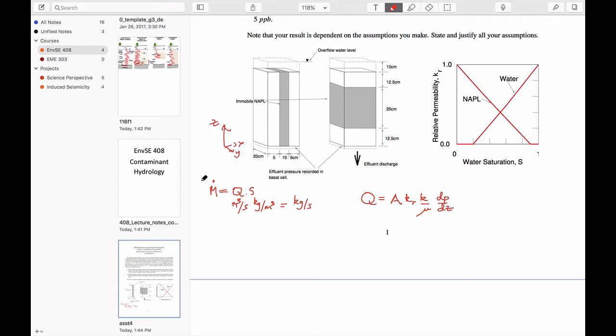And so we have to remember, when we're dealing with this, we had this long discussion about whether we would use pressure gradients or head gradients. We know that this isn't completely right, because in the vertical orientation, if we have a pressure gradient which is finite, it would suggest that we have flow. But if it's just a hydrostatic gradient, there will be no flow. And so what we need to do is replace this in the easiest possible way.